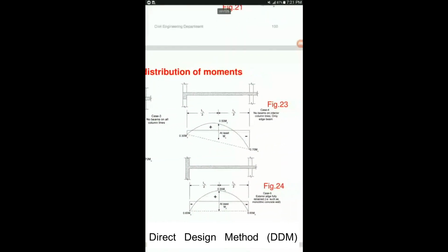The fourth case is showing that there is a slab system. Slab is resting on the exterior support. There are beams and the beam is resting on column, but for the interior support, the slab is resting directly on column. There are no beams here. So this is again a flat plate slab system with exterior beams. I already told you that flat slabs and flat plate slab systems don't have interior beams. You will never see interior beams here, but there is a possibility that they can have some beams running on their exterior peripheries. So this is a flat plate slab system.